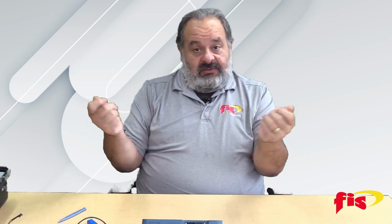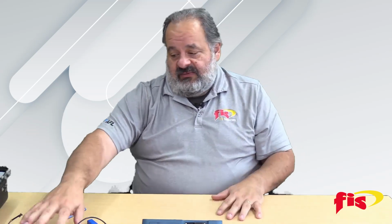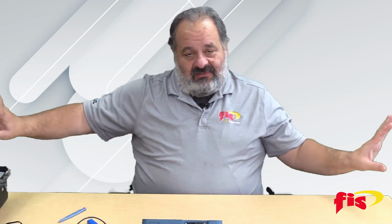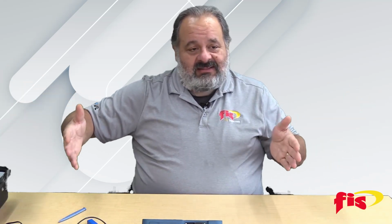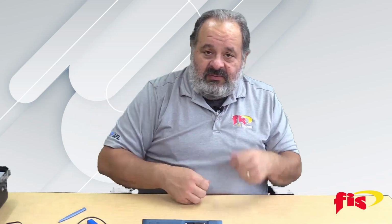So we're going to plug that in, and I'll show you how the OTDR won't report on the attenuation values. And then I'm going to add launch cables. You can see a launch and receive cable on the ends where we sandwich that test cable in the middle, and that will allow us to test the first and last connector. So we're going to swing around here, and I'm going to hook everything up, and we'll do a test.